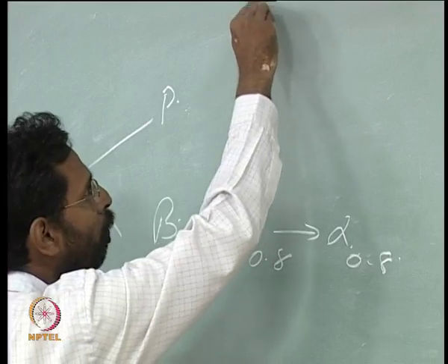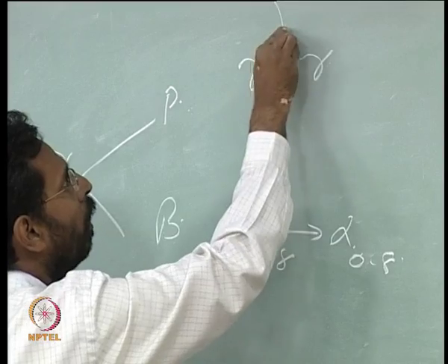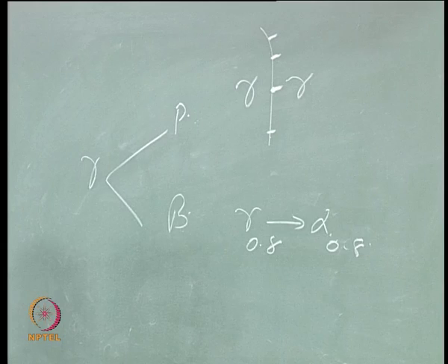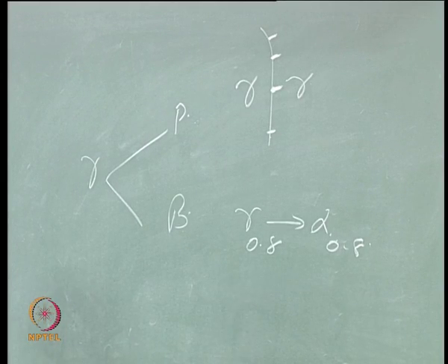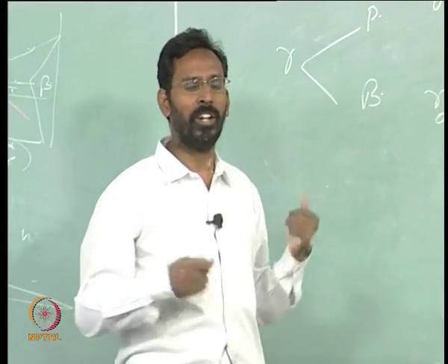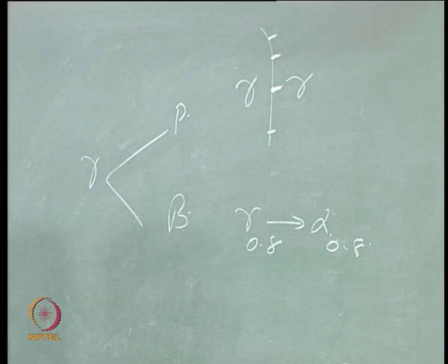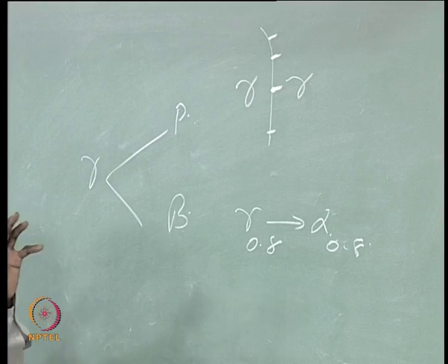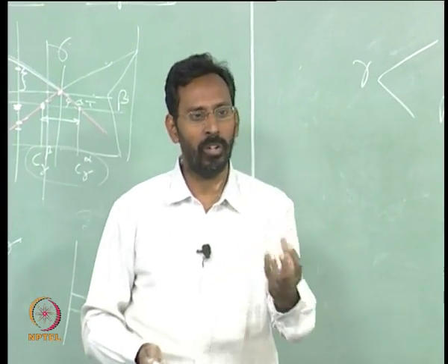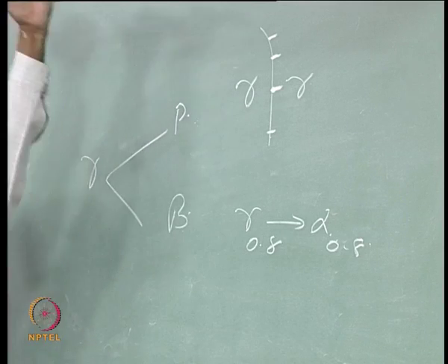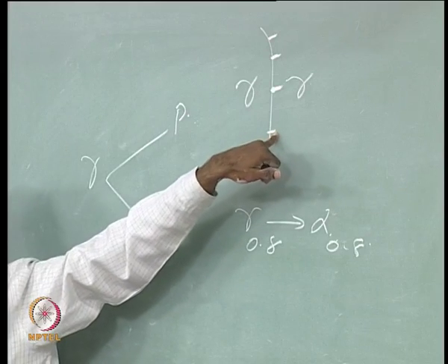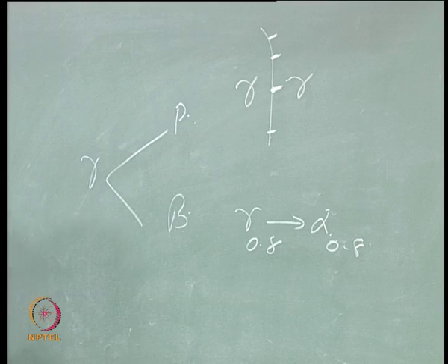Here the carbon is able to move. So, what happens is carbon would come to the grain boundaries of gamma and form small regions of enriched carbon. Once that enriched carbon region reaches 6.67, or 25 atoms out of 75, initially the number of atoms of carbon is very small, it is 0.8, that is weight percent. If I convert it into atomic percent, you would still get possibly about 2 or 3. So, 3 atoms or 4 atoms of carbon in 100 atoms of iron, something like that. That is the initial state. From that initial state more carbon atoms come from a different region, and so that region becomes 25 atoms, then you can easily form a nucleus. That is the reason why, and carbon can happily move at temperatures closer to 723. So, that is the reason why cementite is a nucleus there, whereas here cementite is not able to be a nucleus, carbon is not able to move.